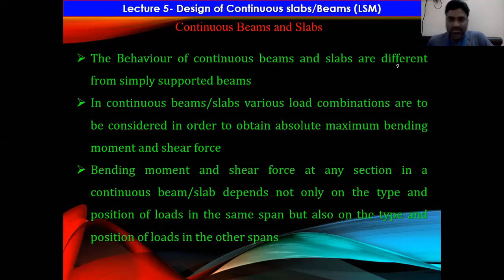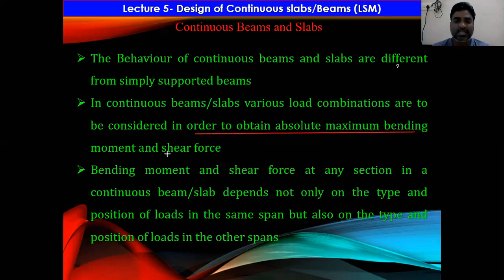Now we'll discuss the behavior. That means what is the behavior of continuous beams and slabs, how they will behave. Right. So the behavior of continuous beams and slabs is different as compared to simply supported beams, because in continuous beams the load combinations are to be considered in order to obtain the absolute maximum bending moment and shear forces.